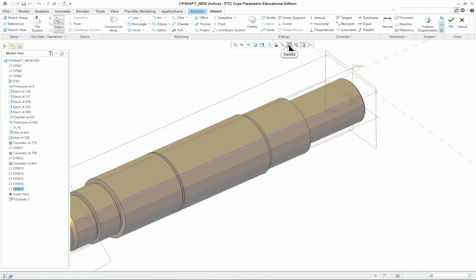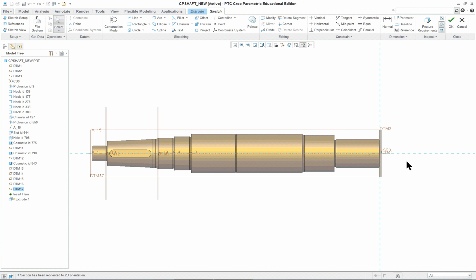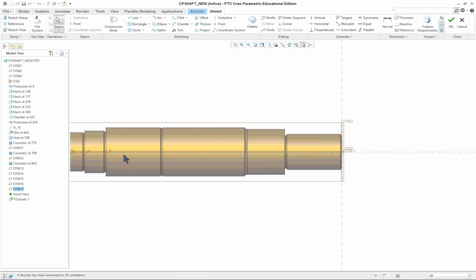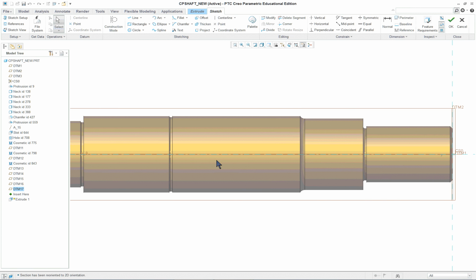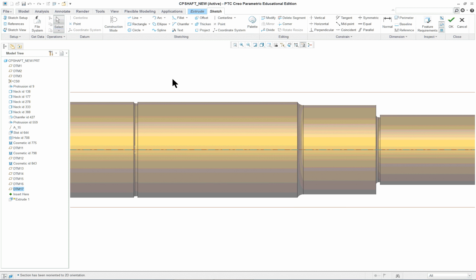And let's go into our sketch view. And we're going to build this slot in here. I'm not going to worry too much about precise dimensions here. So the easiest way for this slot to be created is to use circle and create two circles that are identical. Make sure you watch the references as they come up.